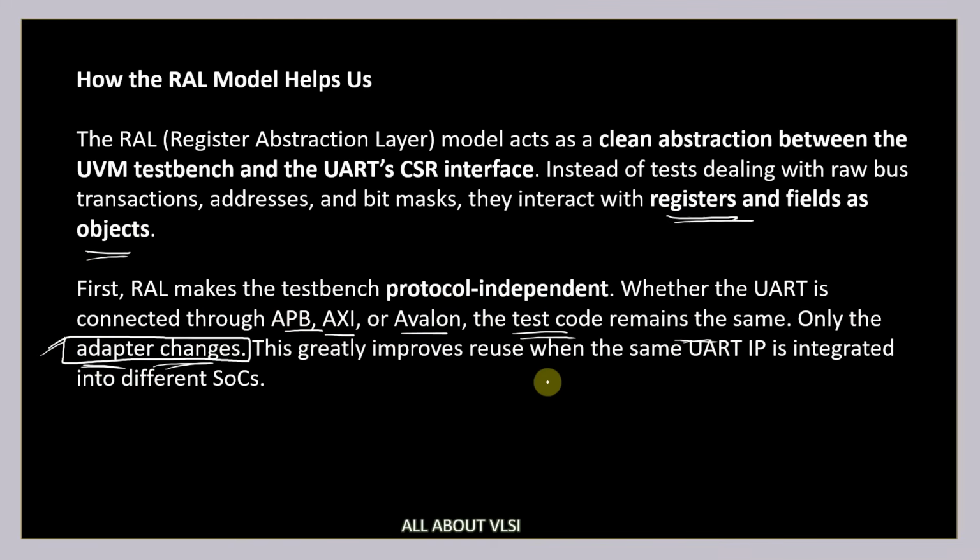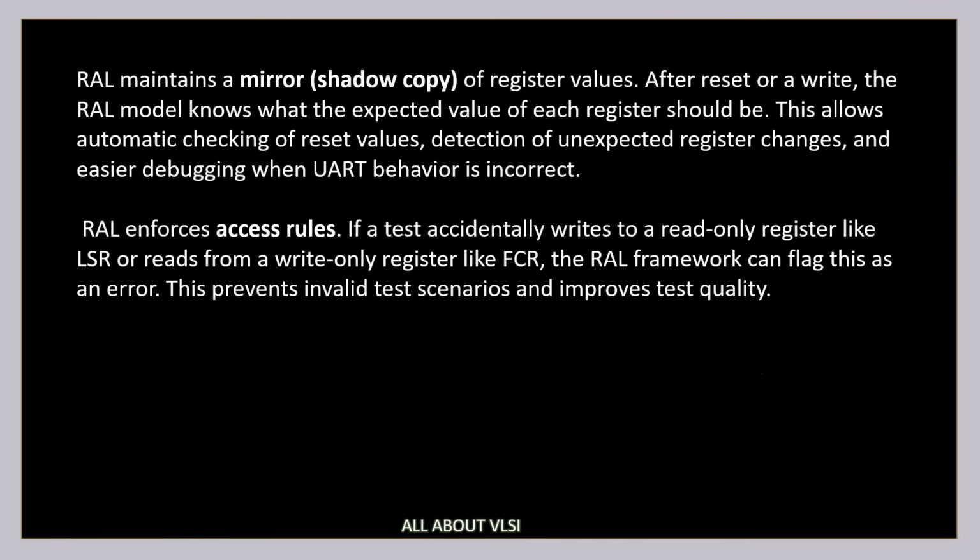This greatly improves reuse when the same UART type is integrated into different SoCs. The RAL model also maintains a mirror or shadow copy of register values, which we have discussed previously. So the RAL model knows what the expected value of each register should be. This allows automatic checking of reset values and detection of unexpected register changes.